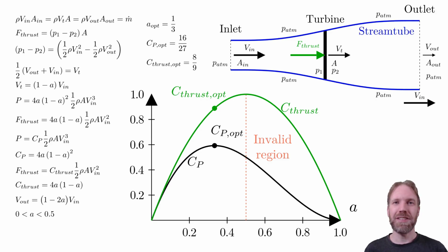In reality, we would expect even larger thrust coefficients if we manage to get that large axial induction factors. This is due to momentum conservation, as we would have a larger change in flow velocity. We can also add in the line for the mass flow. This shows us that larger axial induction factors give lower mass flow through the turbine.